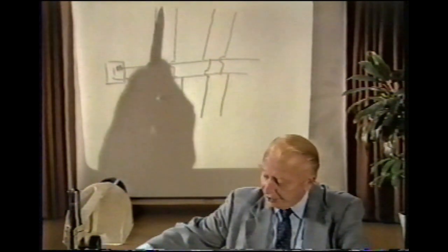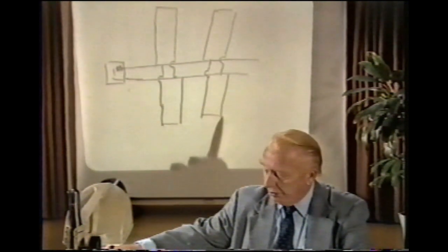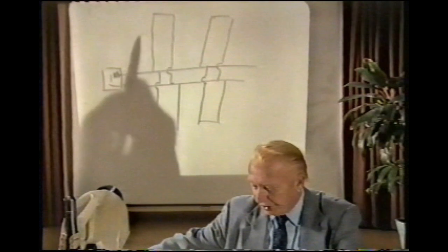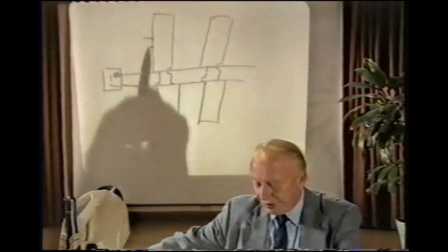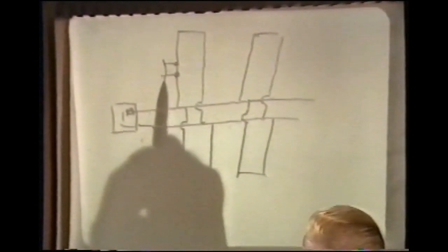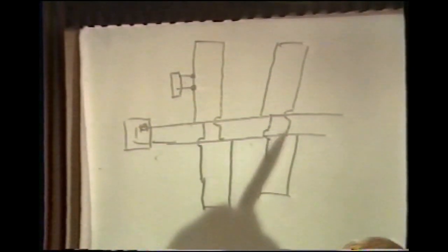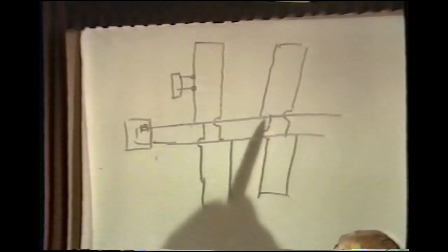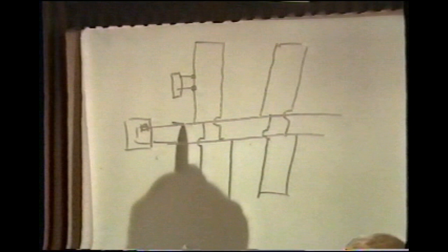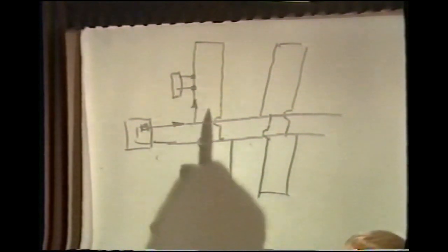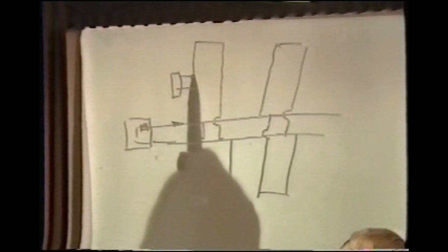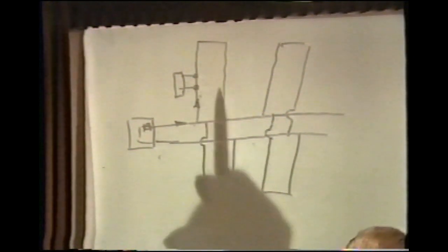The engineer, in terms of design of the building circuits, oversized the piping in those building circuits to the extent that it was difficult then to force the necessary flow rate through those building circuits in order to have flow diverted by the monoflow fittings into the radiation. At the same time, the person designing the distribution system undersized the piping so that we could not provide sufficient flow rate from the distribution main and into the garden-type apartment buildings to provide the necessary flow rate through the monoflow fittings to cause diversion, to cause the radiation to heat.